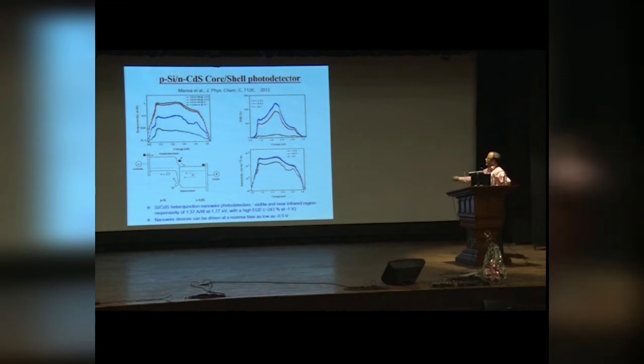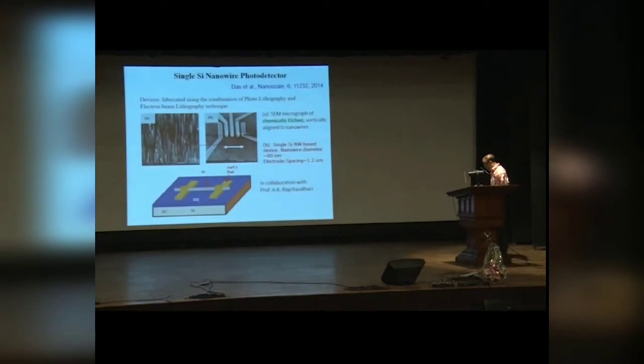The hole mobility of cadmium sulfide is very, very low. So, of course, there is always a kind of electron accumulation. To neutralize this, so there should be no charge accumulation, a lot of electrons are injected from the cathode material, that's why we get this kind of gain. So, this is not really the gain in the true sense, but on the other hand your responsivity is higher than the commercial silicon device. And the detectivity is also quite good enough. Normal silicon device is about 10 to the 12 Jones. So, it's very, very comparable.